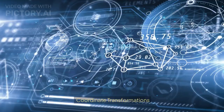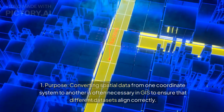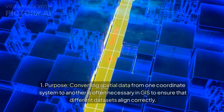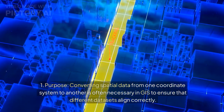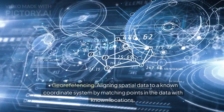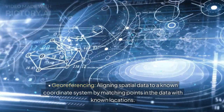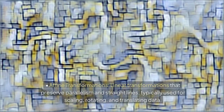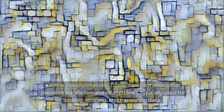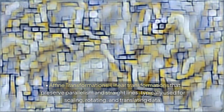Coordinate transformations. 1. Purpose. Converting spatial data from one coordinate system to another is often necessary in GIS to ensure that different datasets align correctly. 2. Transformation methods. Georeferencing. Aligning spatial data to a known coordinate system by matching points in the data with known locations. Affine transformations. Linear transformations that preserve parallelism and straight lines, typically used for scaling, rotating, and translating data.